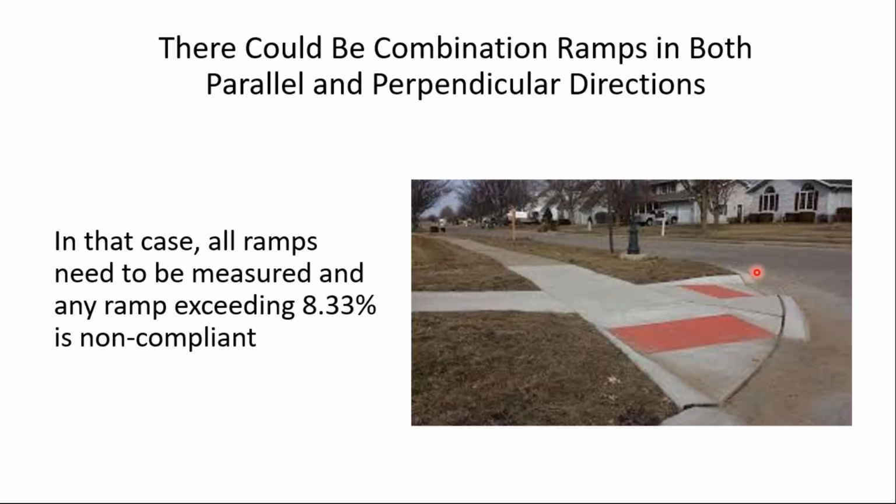The reason I'm not a big fan of that is it doesn't give a whole lot of guidance to the visually impaired. Whereas here with the directional ramps, they have a little better guidance to find their way, to navigate across the street. It lines up better with the sidewalk and ramps on the other side of the street. But I'm sharing my opinion with you.